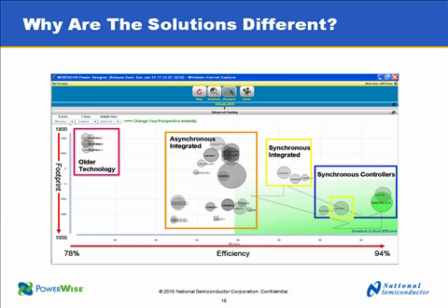Now, as you get into the middle section there in the orange, you've got asynchronous integrated switch devices. These tend to be relatively easy to use. They've got onboard MOSFETs, and typically they're simple, but they're a balance between efficiency and footprint. As we move over to the right and we see the yellow highlighted areas, these are synchronous integrated switch devices. What these have is 2 MOSFETs on board, and they get higher efficiency.